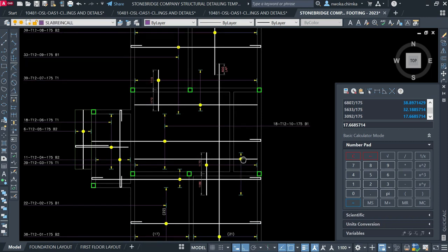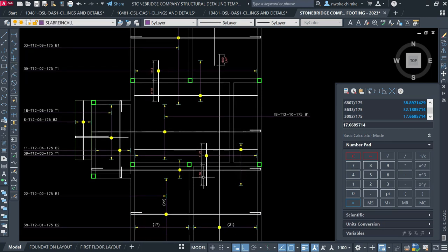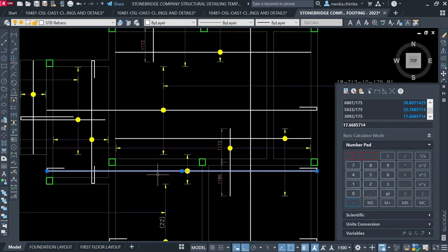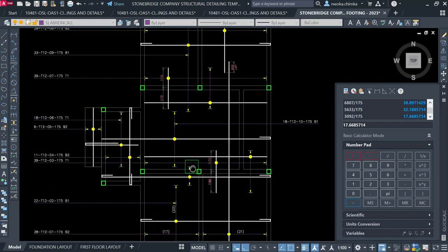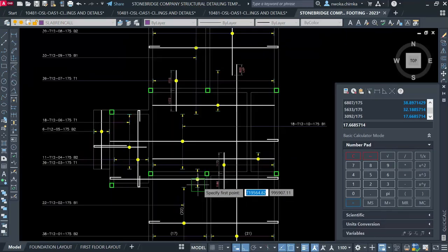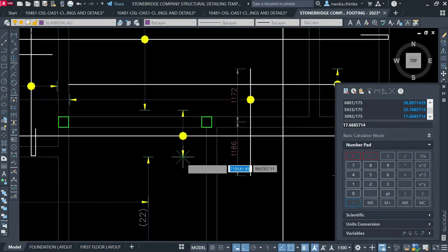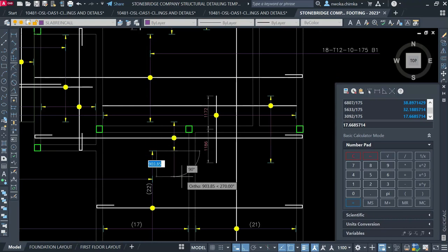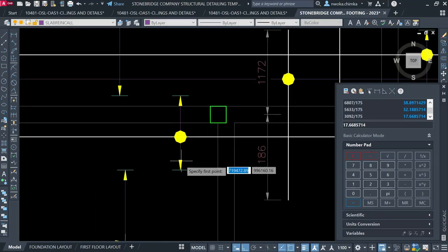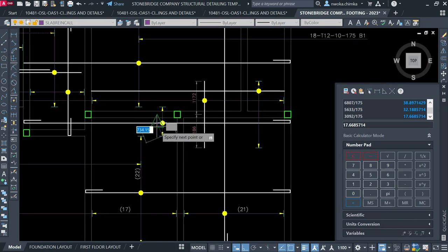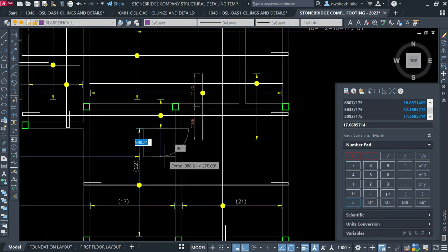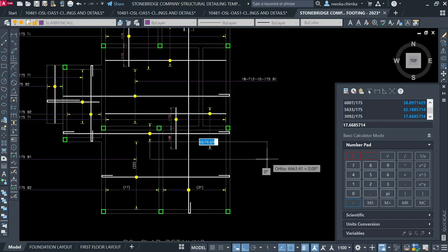First of all, I think we are forgetting one. There is one we are not calling out, which is this bottom bar here, and it is just running from this point to this point here. So let's call it out. If you don't have space to call out a bar, there is an avenue for you to bring it out like this. To call out this bar here, I can bring the line from here out, point it down here and bring it out like this.